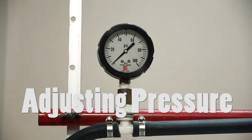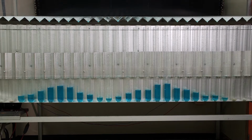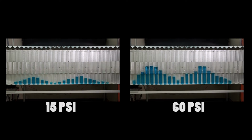Another way to change an application rate is to adjust the pressure. In this demonstration, we will start with a pressure of 15 pounds per square inch. From the 15 psi setting, this is the amount of water collected in the tubes. Next, the pressure will be increased to 60 psi. A higher volume of water was collected in the tubes when the pump was set to 60 psi. Looking at both tests side by side, we can see the difference in volume output at 15 and 60 psi.